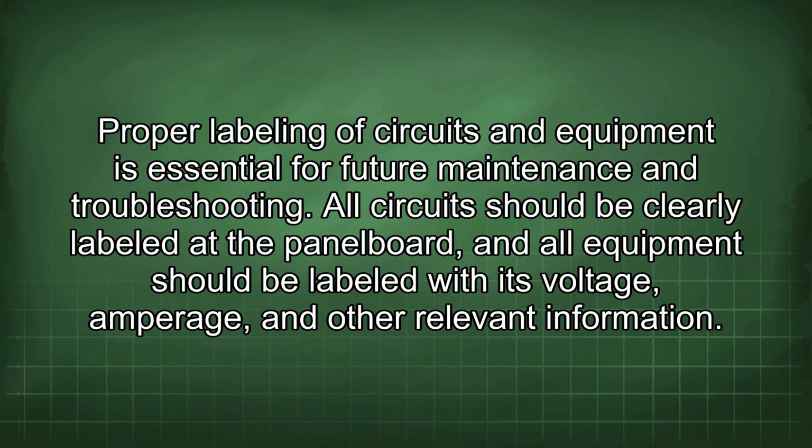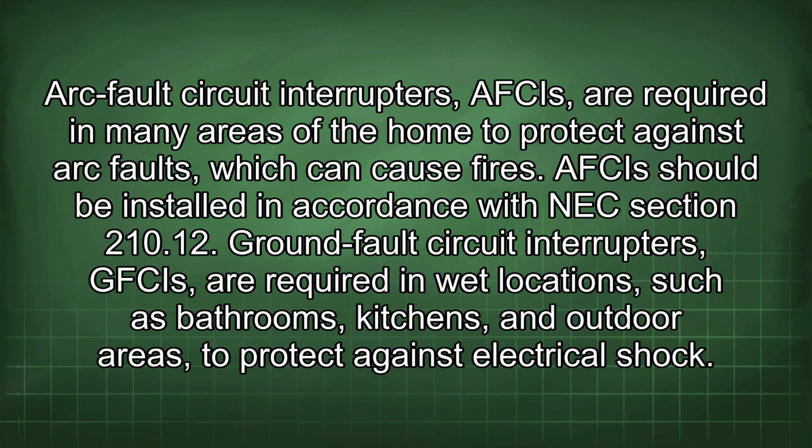Arc fault circuit interrupters, AFCIs, are required in many areas of the home to protect against arc faults, which can cause fires. AFCIs should be installed in accordance with NEC Section 210.12.